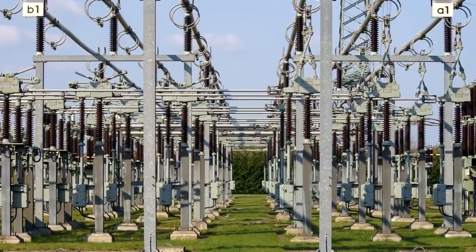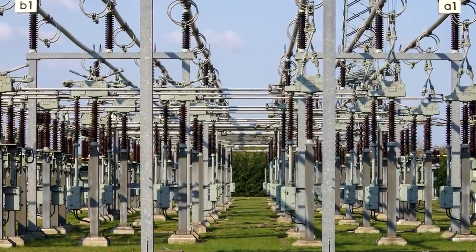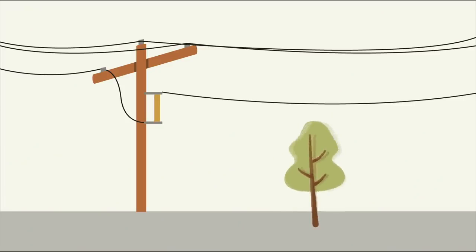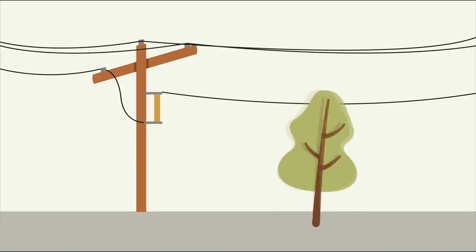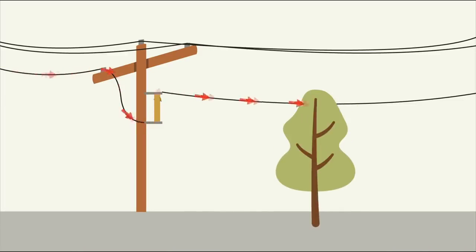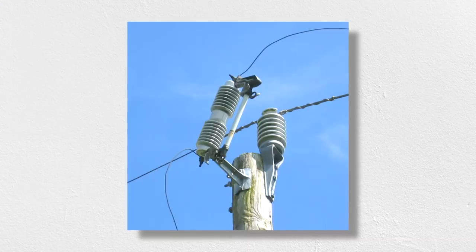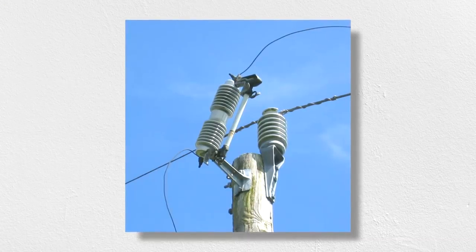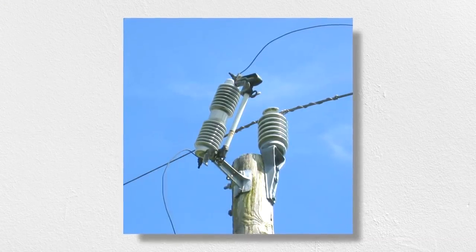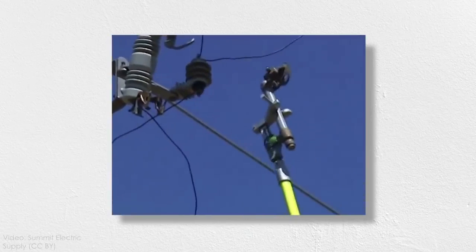Many of the ways we protect equipment from faults are handled at a substation. One of the most common types of electrical fault is a short circuit to ground. This type of fault creates a low resistance path for current to flow and leads to an overload of power lines and equipment. The simplest way to protect against this type of fault is with a fuse, a device that physically burns out at a certain current threshold. Fuses are dead simple and don't require much maintenance, but they do have some disadvantages too. They're one-time use, and they can't be used to interrupt current for other types of faults.